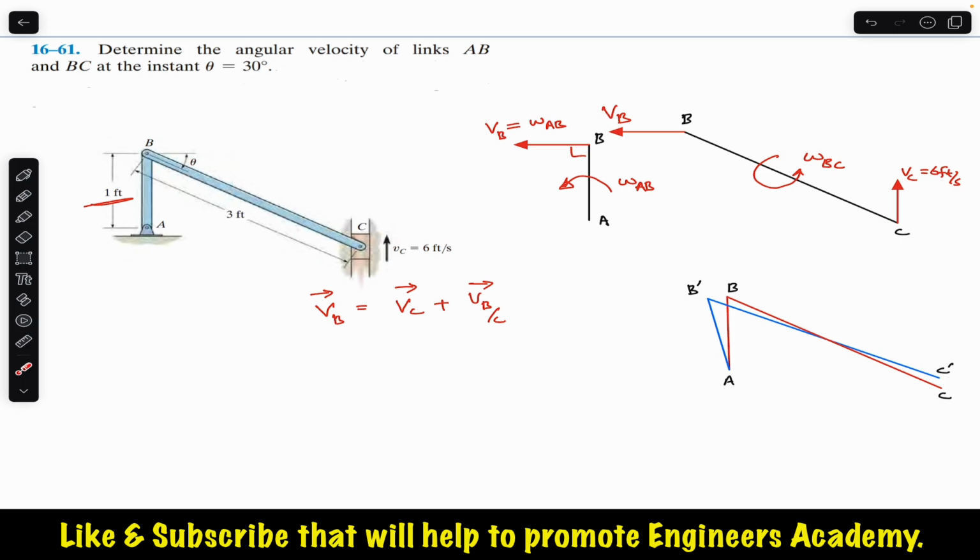From here we can see that point B moves toward this side. So the angular velocity is like this, in the counterclockwise direction. So this velocity of B relative to C is due to this omega BC. So this velocity will be tangent to this BC. If we are talking about the velocity of B relative to C, this point B is moving like this, so this velocity will be tangent. So the direction of the velocity of B relative to C will be in this direction, and this will be perpendicular to that link BC.